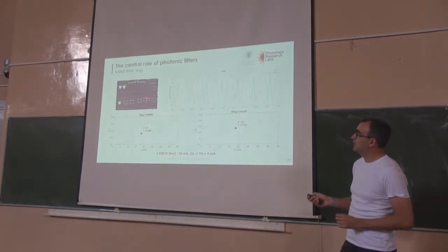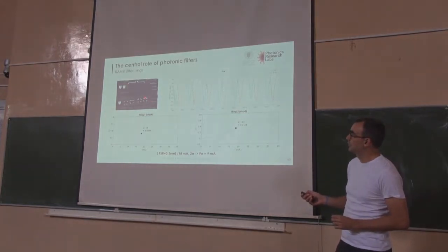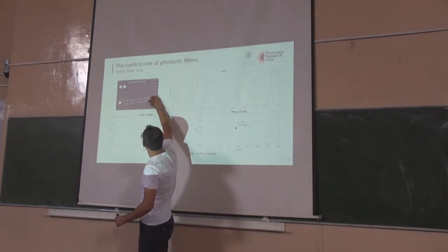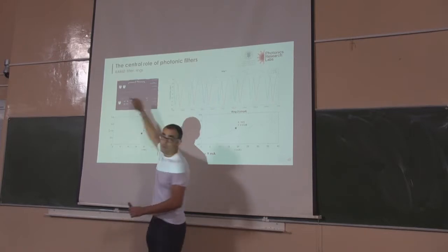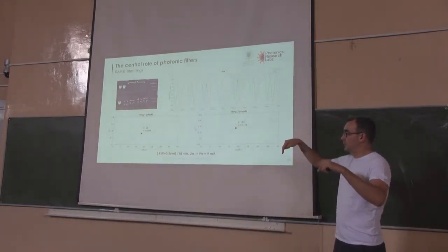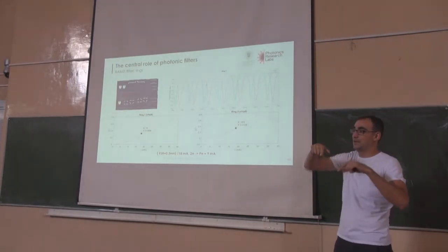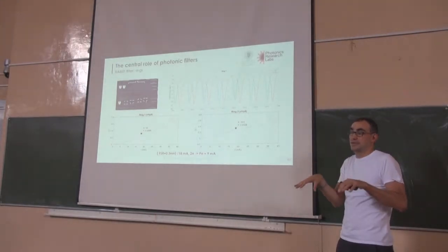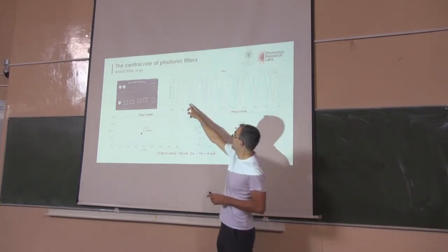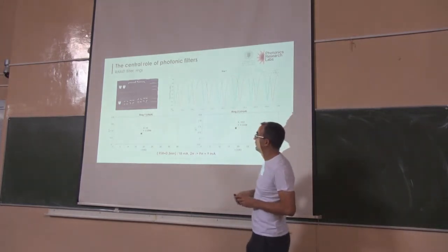Other thing that you have are the ring resonators. These are these small rings here. So you can see them here. Okay, these rings here. And you can see the metal pads going on top of the rings. These metal pads are for tuning the ring. You put current on one pad and it flows to the other pad. So actually it heats the circuit underneath. And that causes, this is the response of the ring resonator, and that causes the response to shift.